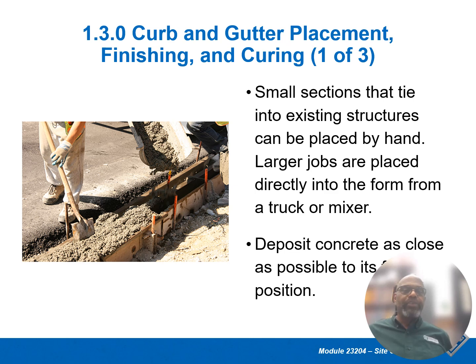So, curb and gutter placement, finishing and curing. This is a picture of them building out a curb. You can see the forms that are used. Small sections that tie into existing structures can be placed by hand. Large jobs are placed directly into the form from the truck or the mixer. Again, deposit concrete as close as possible to its original position. You can see where they are adding the concrete right there in the form and setting it. They're going to screed it and float it out and so forth.